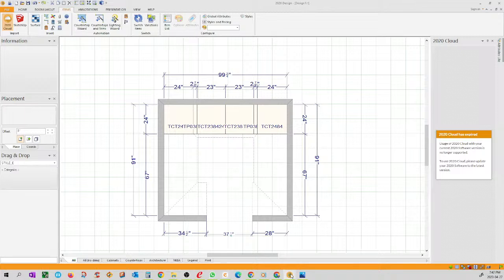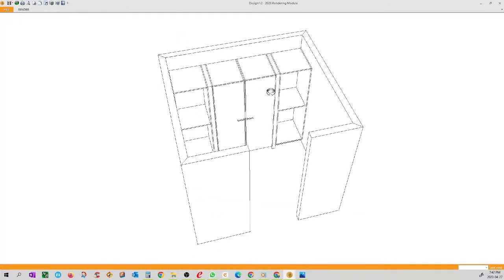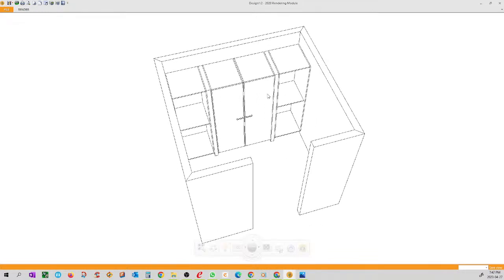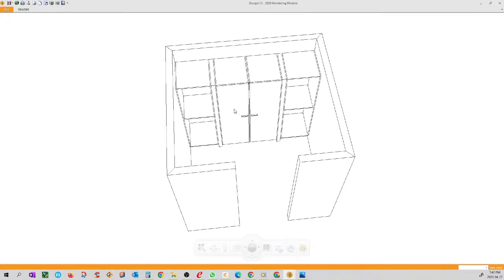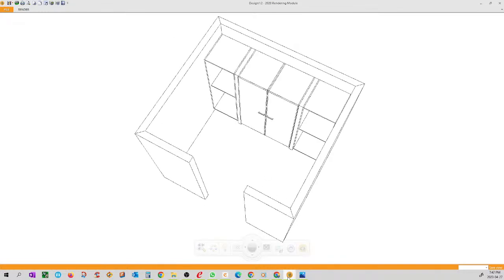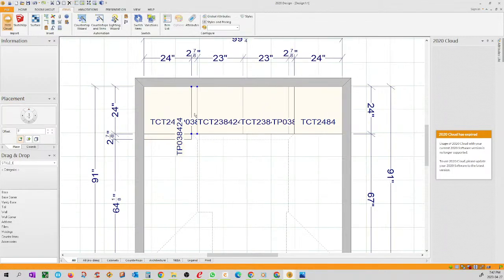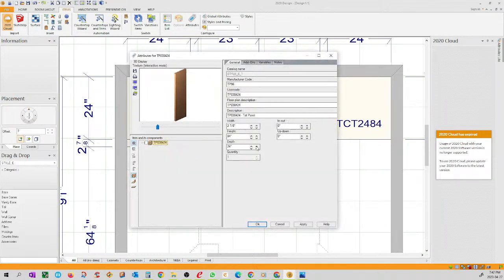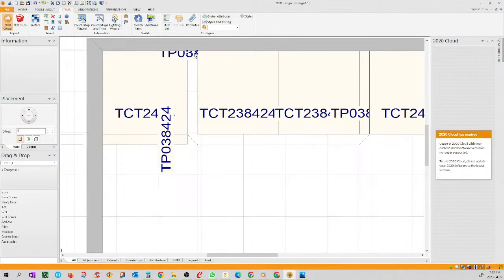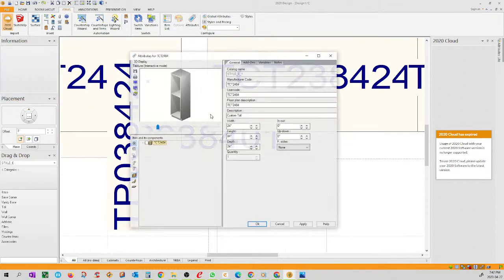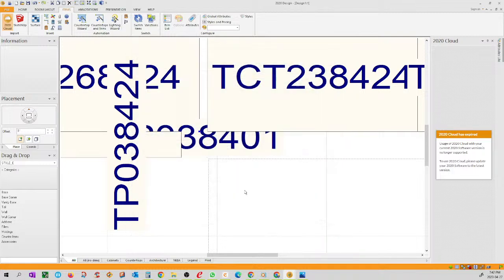So these are the blind cabinets. Now everything we built this way, this would be a shelf with the long hang. You open this door and the cabinets continue all the way, so you can store stuff behind, like winter stuff and stuff that you don't use as often. In order to understand this better, this is actually going to be only 0.875, so this is going to be in like that, and in and out like that, and then we can increase this by 2 inches. So there we go.